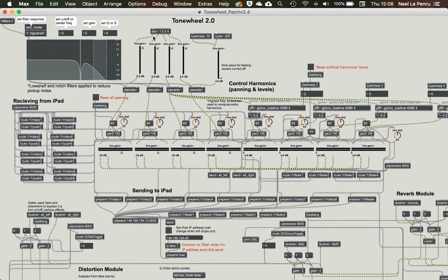So it begins here where we get from the Focusrite Scarlett 18i interface, we use 4 inputs that are mapped such that we can just use 1, 2, 3, 4 here, and that's from each individual pickup. And actually the first thing that happens after these is they're sent through 2 filters. That's why we use Cascade in this case. There's a high shelf filter to get rid of some high frequency noise, and a notch filter that's trying to eliminate some other background noise that was specifically around this frequency.